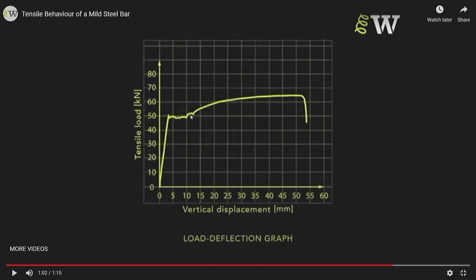And then what happens is the material plane slips past another, and then ultimately at a point, in this case when vertical displacement is 10 millimeter, they start to lock up again, and the load starts to increase. And finally the failure happens at, in this case, about 65 kilonewton load.